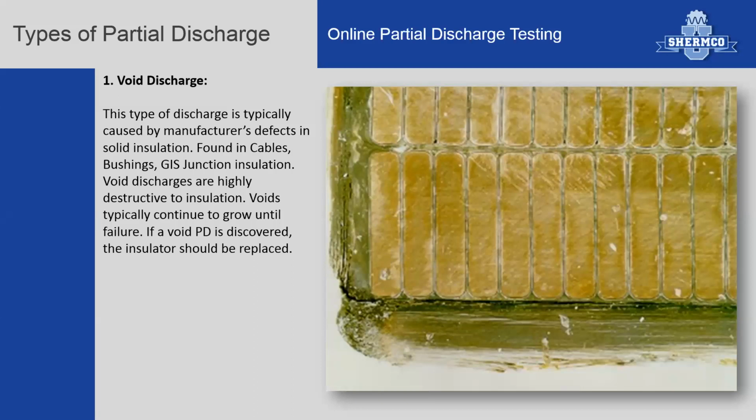In the slide, the image, I basically show a motor winding, like for instance, in a stator. And the voids that we see here are delamination or gaps in the mica insulating tape. Now here again, since mica is used as the insulation, we may have partial discharge activity in these voids for a very, very long period of time before they can finally erode and break through the ground wall insulation.